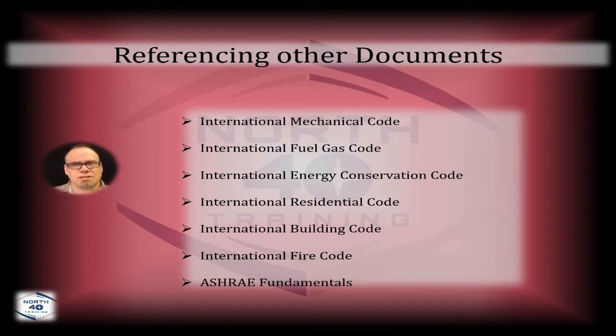The exceptions to some will be a much bigger portion of the code than the code itself. The exception is any dwelling unit 3 stories or less under rooftop with an egress window and any accessory structures, those are going to be referenced over to the International Residential Code. Now, what does that mean?